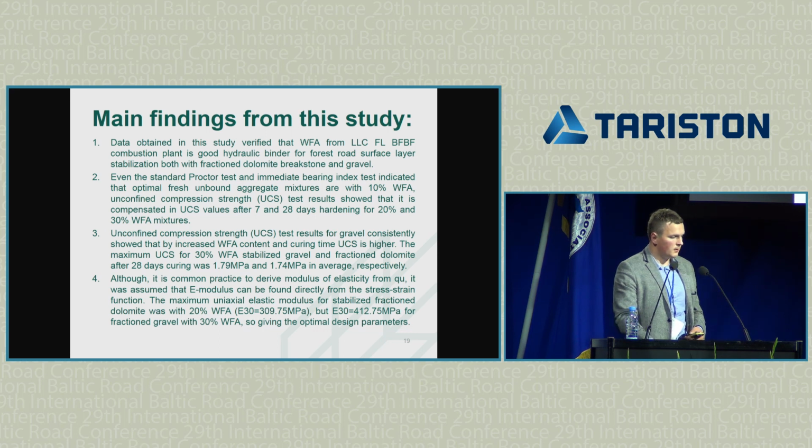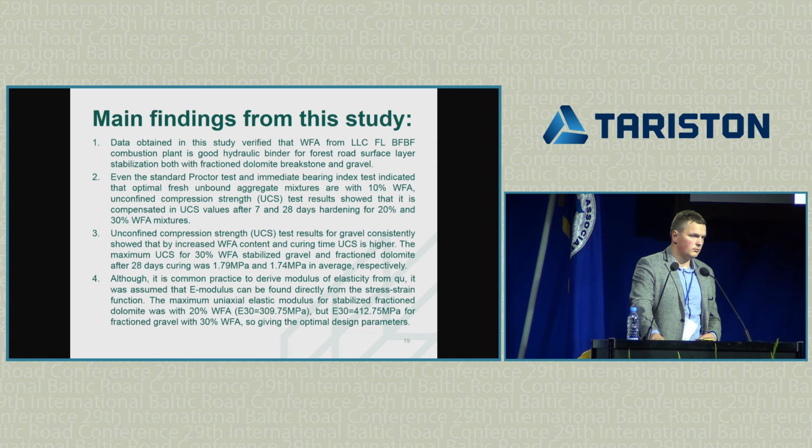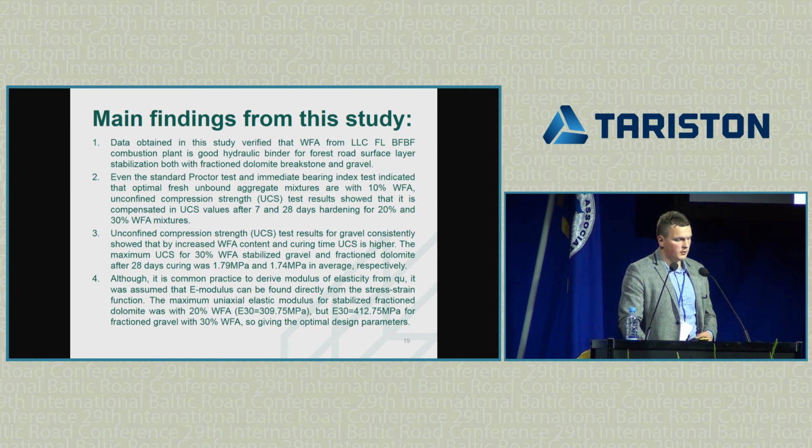But here in the first two stages, we determined, or we are now sure, that this wood fly ash from the Fortum Latvia bubbling fluidized bed combustion plant is a good hydraulic binder for forest road surface layer stabilization. It's both for fractional dolomite breakstone and gravel.